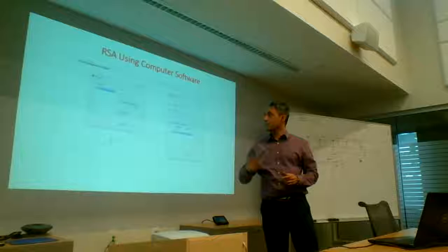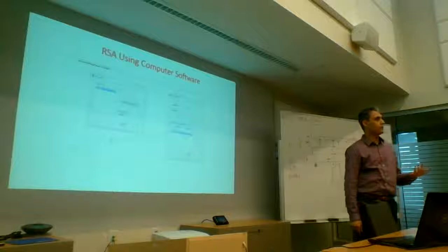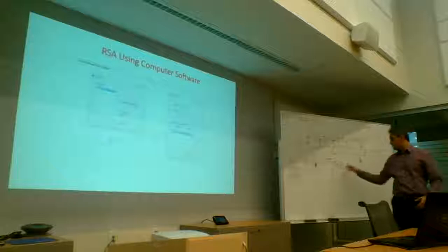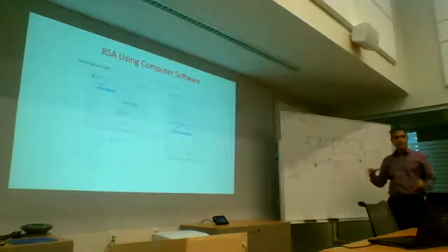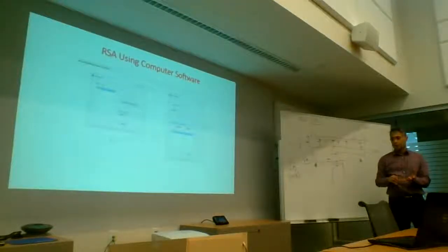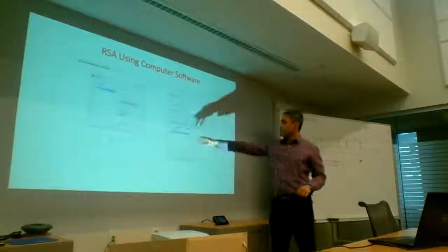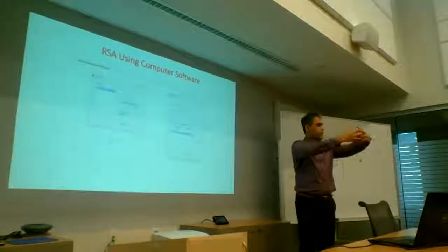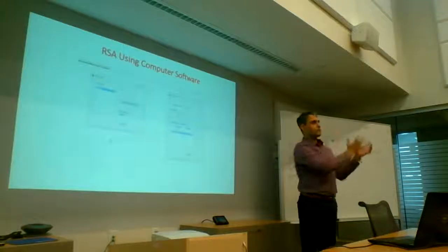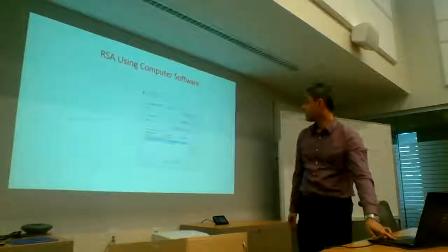SAP, or CSI Bridge, also asks you to tell it the mass source. Where is my seismic mass coming from? It could come from just the deck. It could come from the elements. You might also have a lumped mass somewhere if something heavy is sitting somewhere, which you may not have modeled in the bent itself. So you can assign a load to a joint, and then in the mass source, you can actually say, take my members, take all the loads that I've applied, and turn all of those into seismic mass. Okay, and your program can do that. So keep those in mind.